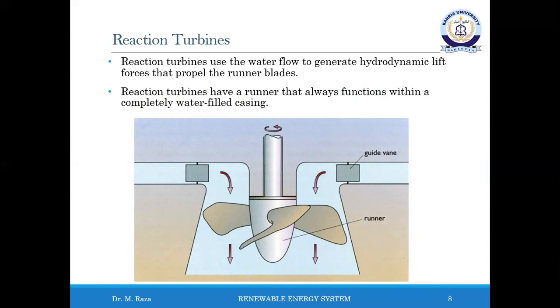For efficiency, the water must have some swirl before entering the turbine runner. The runner absorbs the swirl and the water flow that emerges goes straight into the draft tube. Methods for adding inlet swirl include using a set of guide vanes mounted upstream to conduct the water in a spiral into the runner. Another method is to house the runner in a snail shell so water enters tangentially and is forced to spiral into the runner. Adjustable guide vanes can vary the flow admitted to the runner.